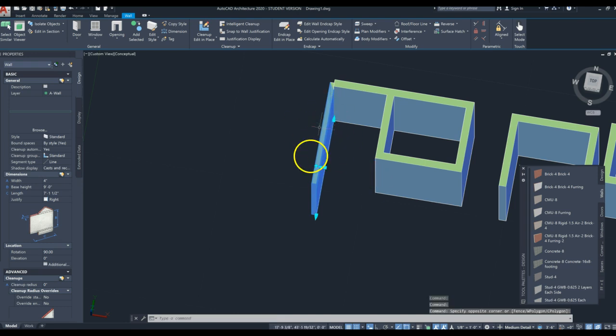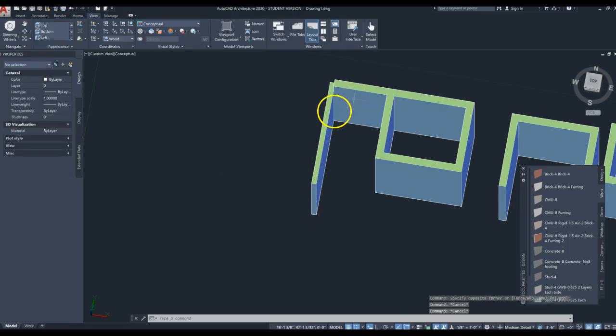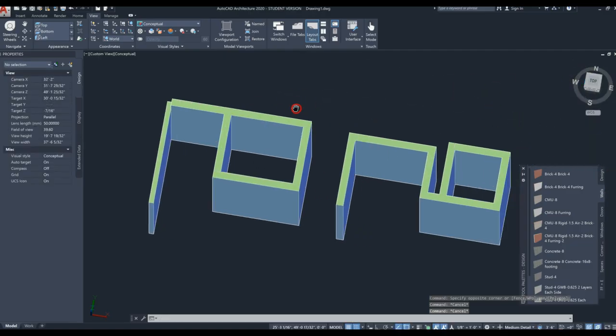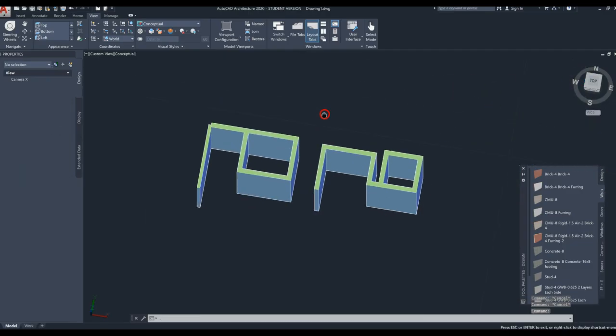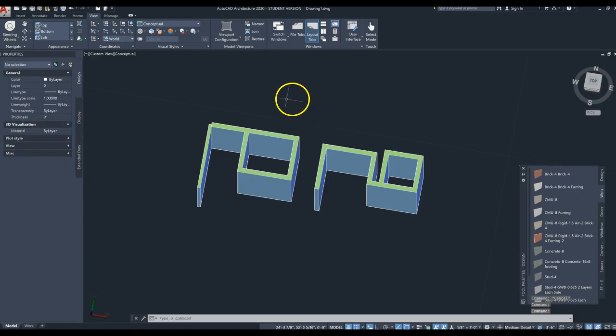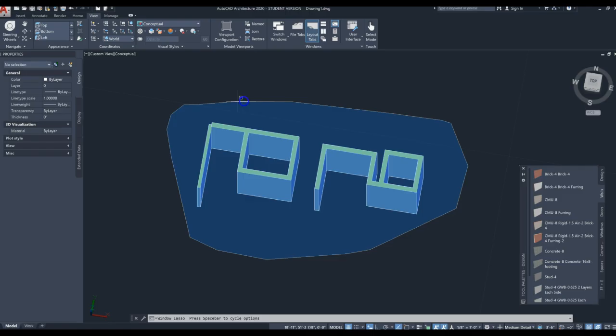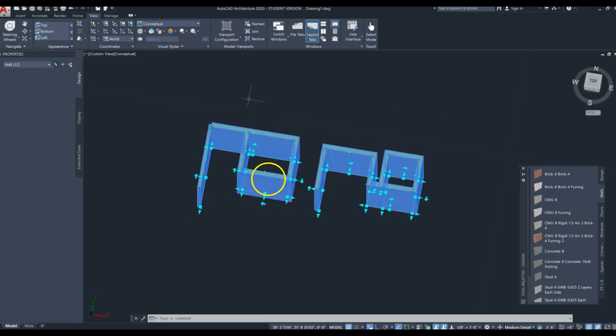So first of all, how do I deselect this wall? Hit the escape button on your keyboard and it's no longer selected. Next, if I want to select multiple things all at once, here's what you can do. Click and hold your mouse just in the black space over here and drag around to trace out and kind of capture everything you see.